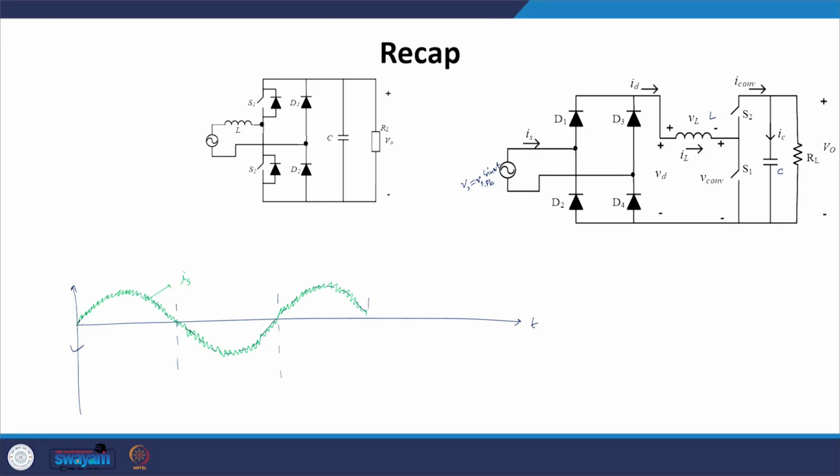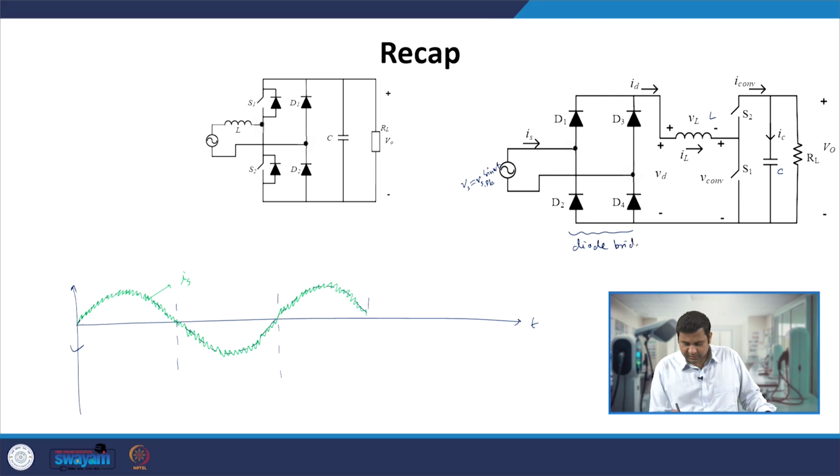Welcome to lecture number 20 of this NPTEL lecture series on charging infrastructure. In this lecture, we will study the DCM operation of boost based PFC converters. In some of the previous lectures, we have studied the operation of the boost PFC converter, which consists of a diode bridge rectifier as the first stage, followed by a DC-DC boost converter.